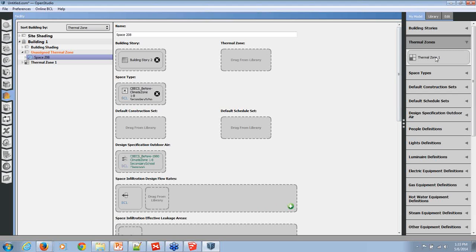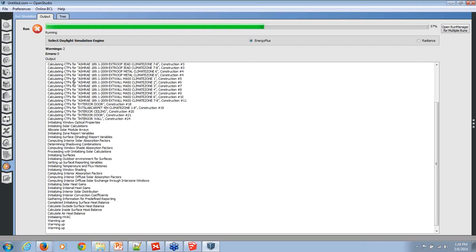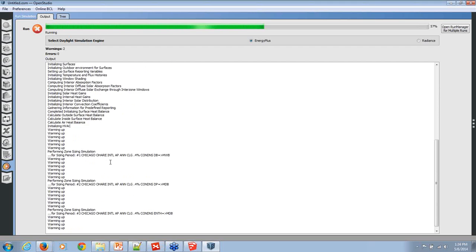So, of course, we don't have a service hot water system and all that. That's fine. But now that we have a thermal zone and an HVAC system configured, let's make sure it'll run. And we'll move it over into PAT and we'll add the AEDG measures. Just to make sure again that this is running. Looks good. We've got it running.